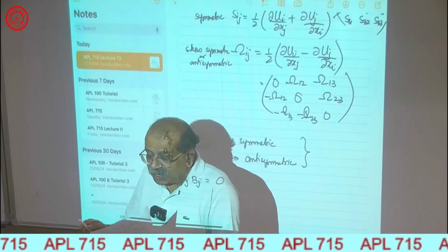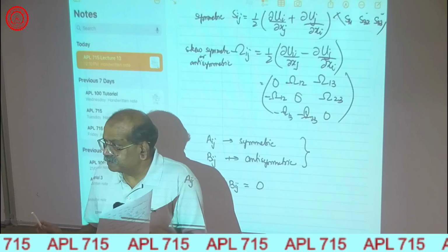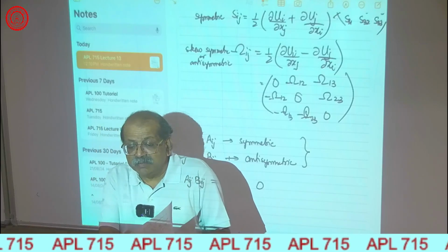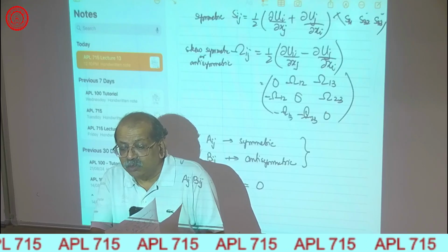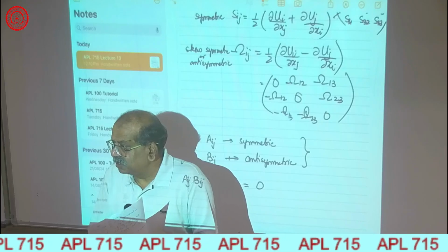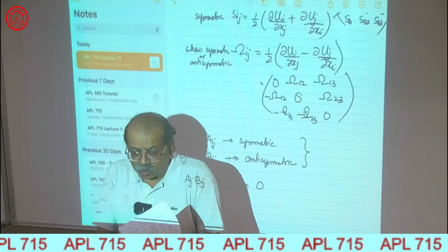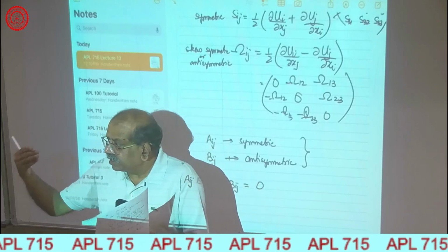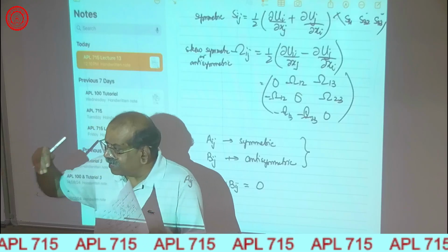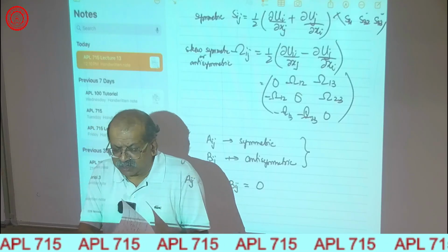And the second trick will come in the dissipation term. In the dissipation term, this equation gives you nu times d2 of u_i prime u_j prime by dx_k dx_k. So what I've tried to show to you is that you write u_i prime u_j prime, and take del square by partial x_k of this term.